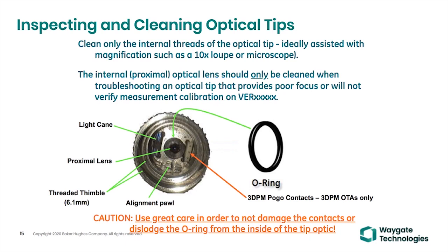And so there's no taking a tip on or off there. You simply use the head optics on that probe. So it's difficult to get oil in there unless there's a damage situation. When using the 4 millimeter product, which has a better optical system in it, that came to the market after the 3.9, you do need to use a tip optic, in this case, a black tip optic, a general tip optic, to have the same visual requirements or optical characteristics as the 3.9.